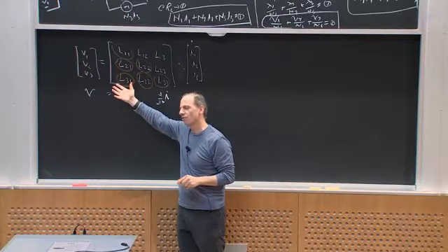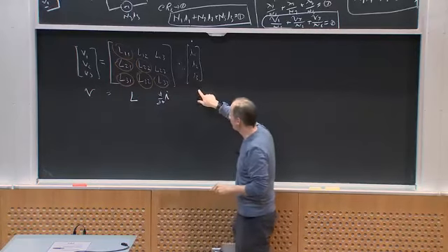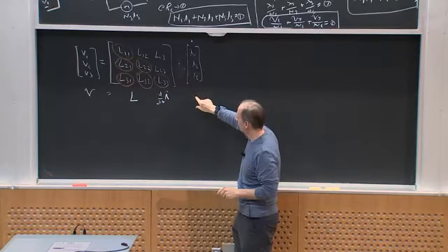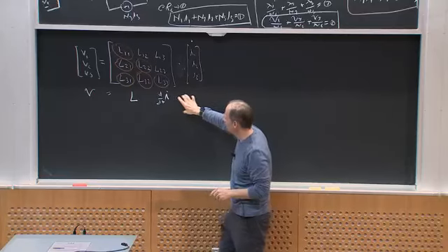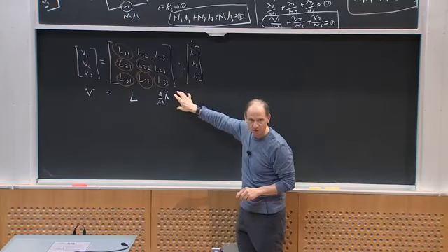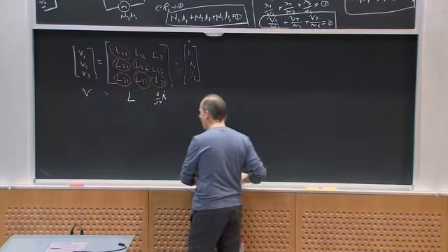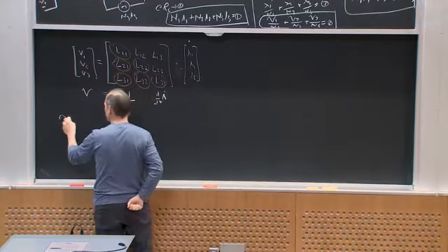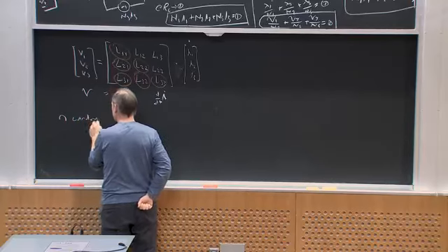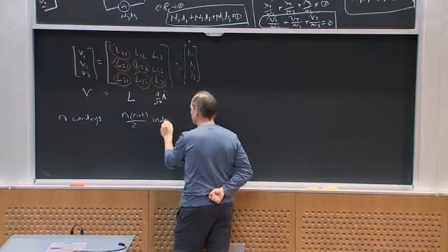What would happen if I had a 4-winding transformer in the general case? Well, I'd add a V4 and an I4, and basically add one more bottom row of independent parameters, 4 parameters, and I'd have 10. So it turns out that an n-winding transformer ends up with n times n plus 1 over 2 independent parameters.